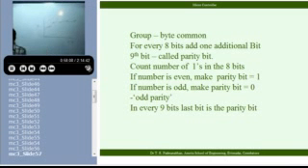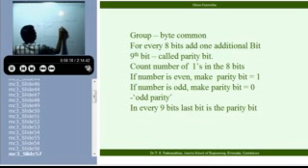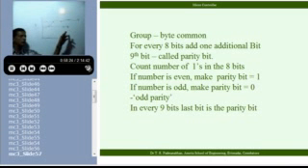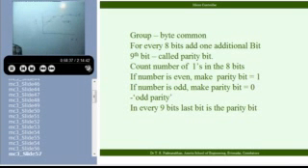This is analog transmission. But if there is some corruption, some noise, some pickup, the value here may be 1.578. Now if it goes to 1.579 or 1.577, there's no way of knowing whether it's the actual value or a corruption. That's what Kumar is pointing out. There's no way of knowing.